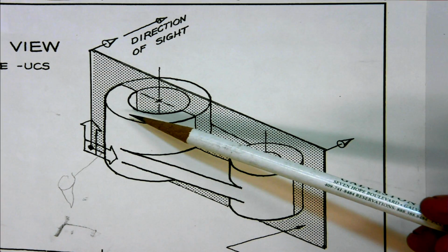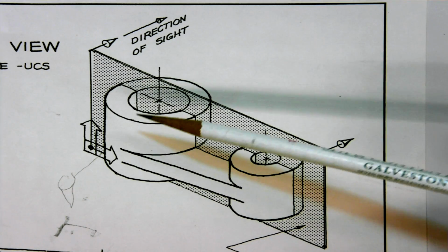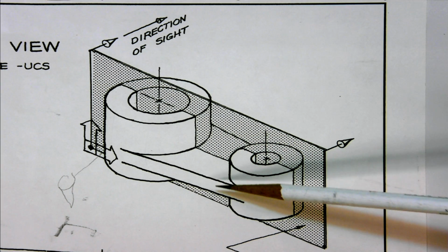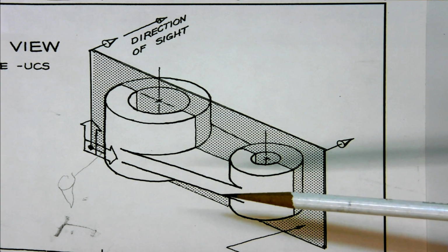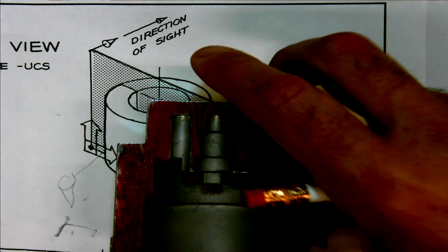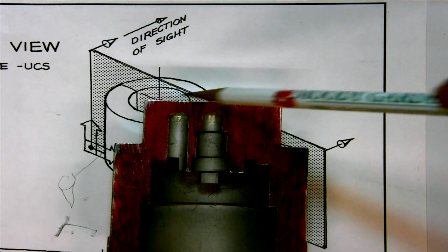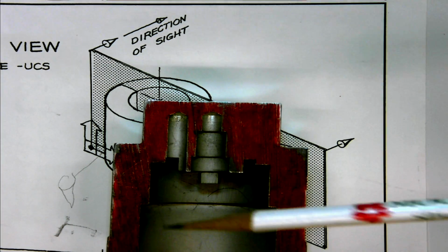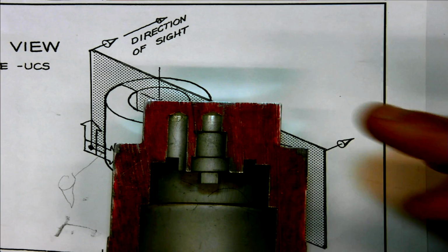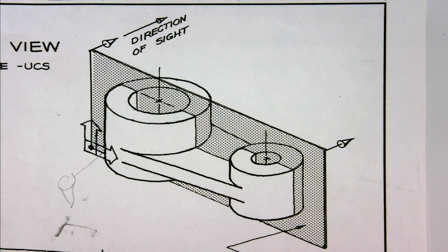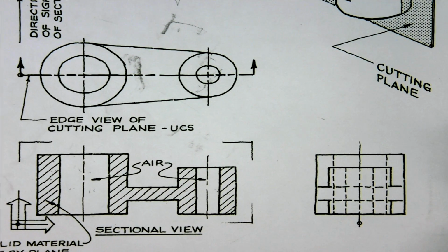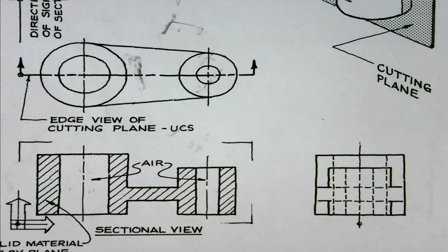Okay, so just like the front part of the other one is removed, in the section view sketch here, this part of the object will be removed. Okay, so then you will expose both the outline of the object, like we have here, everything behind the cutting plane, where it touches the cutting plane along here, and any kind of airspace in between.